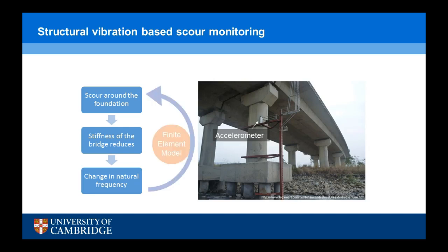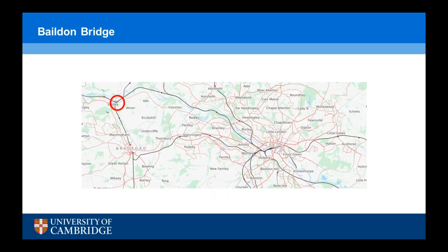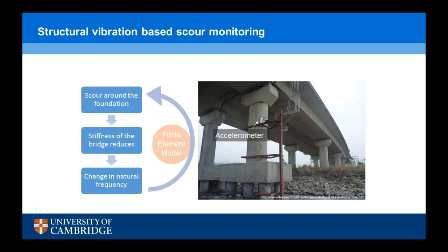We can correlate that back to the scour depth by using a finite element model, or we can use the natural frequency itself as a measure of scour-induced damage. Lots of researchers have carried out numerical models and found that natural frequency is in fact sensitive to scour.